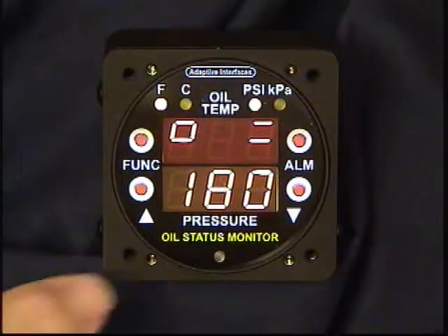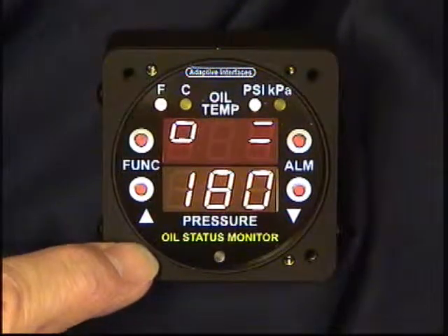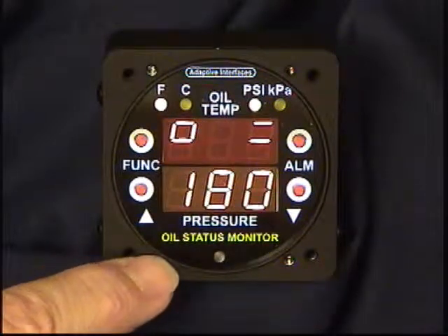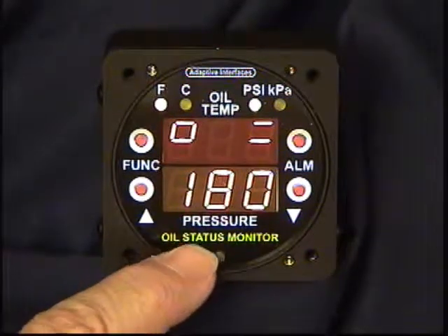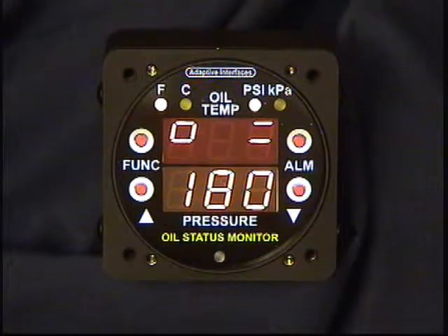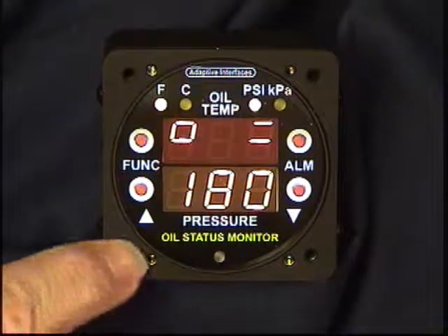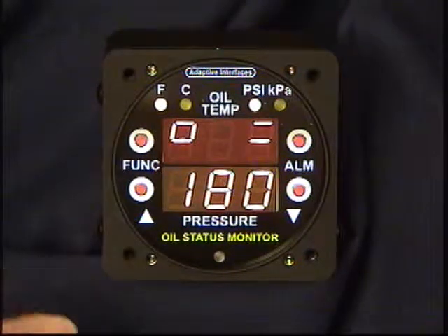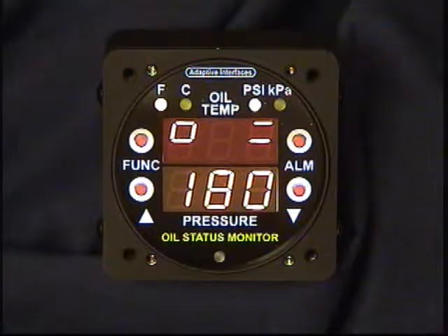The next data point is the temperature associated with the 348 ohms. In this case it's set at 180 degrees Fahrenheit. When setting the data points, they are always set in English values of Fahrenheit or PSI. They are not set in metric.